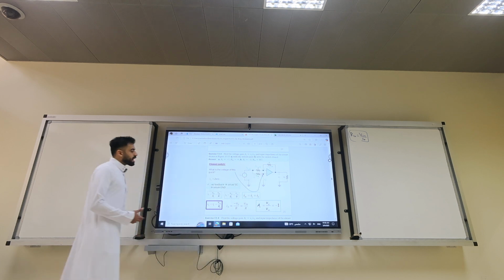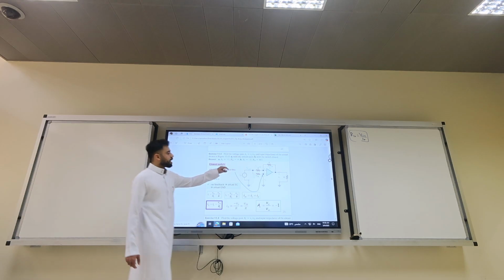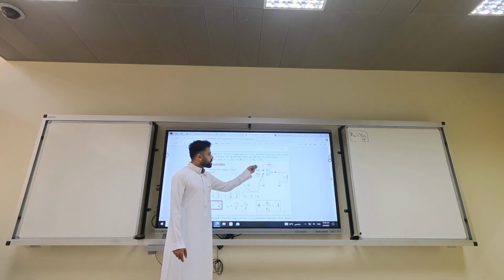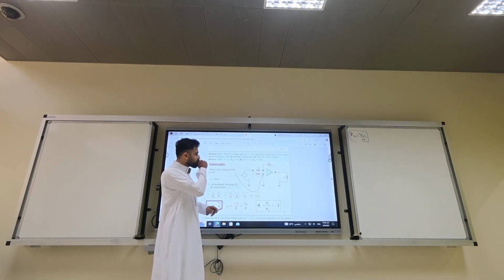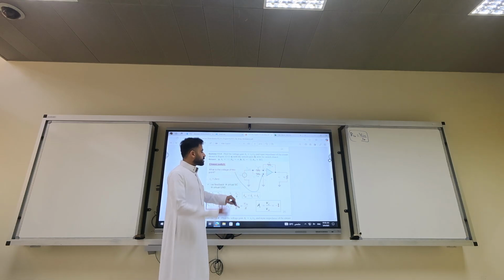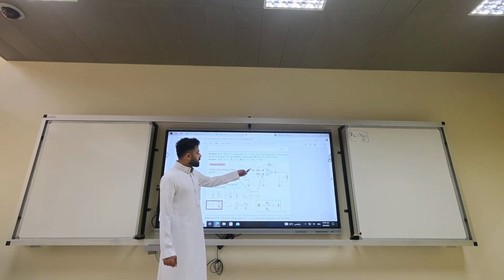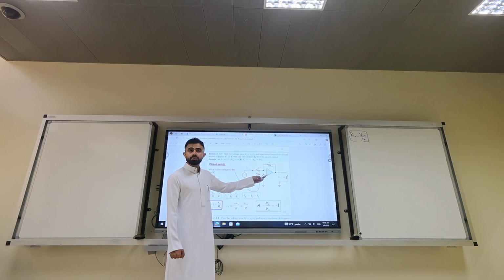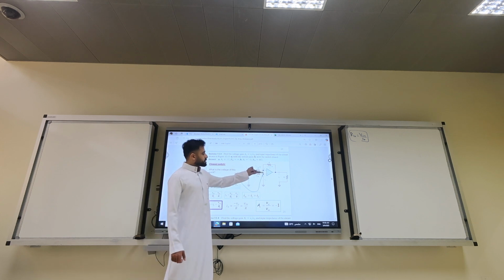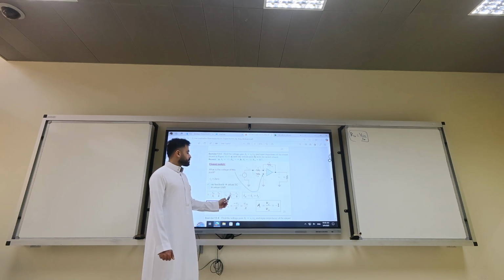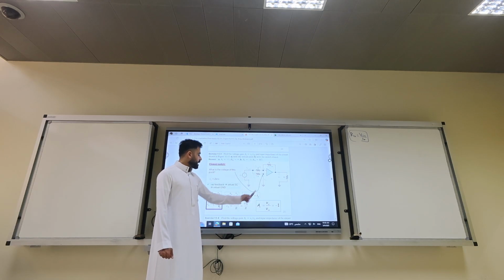And how did we analyze the circuit? We started with I input equals V input minus virtual zero over R. Everything here is R. And we said I2 equals V input minus an actual zero, ground. This is an actual ground. This is a virtual ground. Over R. So both currents are going to split. But we know that no current enters the op amp. So I3 equals I1. And you know that I input is I1 plus I2.